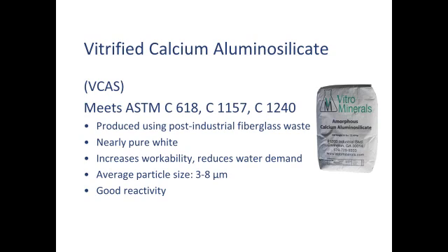The average particle size is 3 to 8 microns, although just like sand, there are all different size ranges. Typically about as fine or finer than cement. It has good reactivity, which is why it's used. So the reason why it's used is it gives you great workability. It's white, so it doesn't affect your colors. You can make pure white concrete with it.